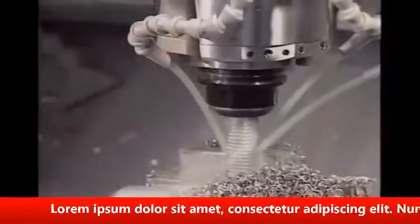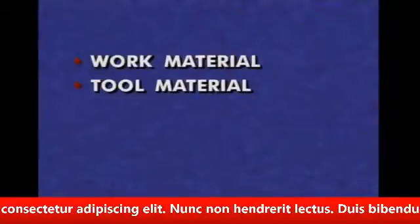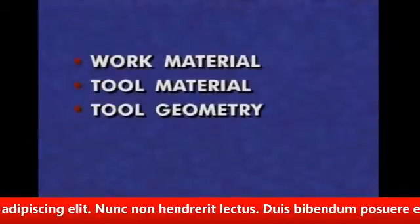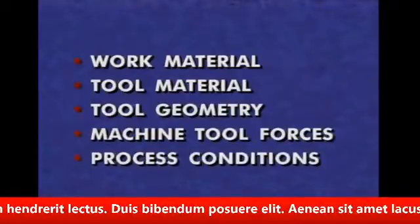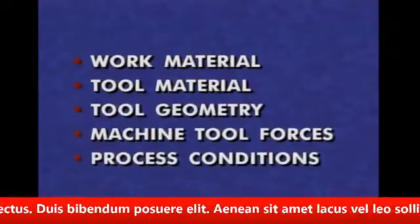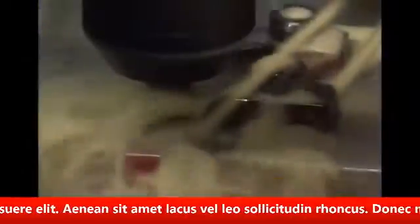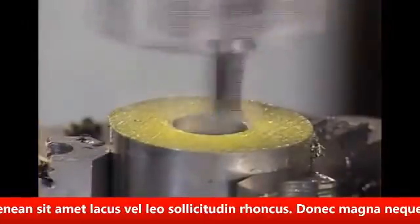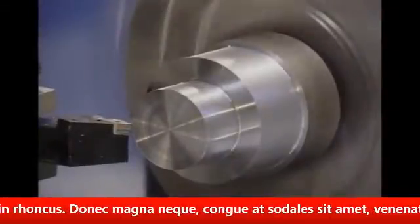How that material failure and chip formation takes place is influenced by the work material, the tool material, the tool geometry, the forces applied by the machine tool, and various conditions in the process, such as heat and vibration. An efficient cutting tool geometry is one that minimizes heat in the cut and achieves a cool, properly formed, manageable chip while cutting the given workpiece material.